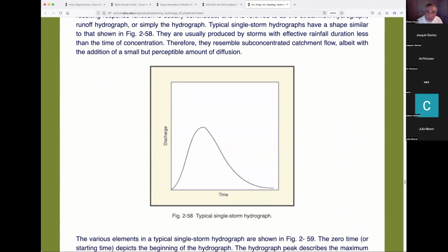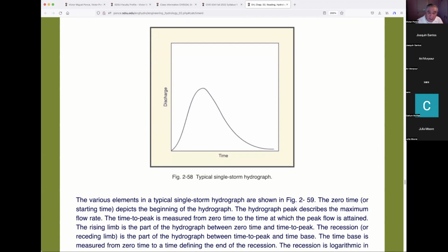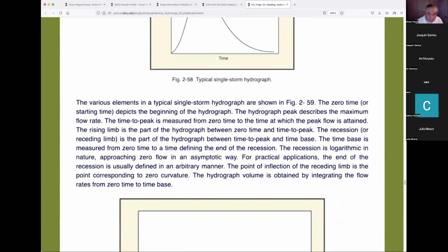It goes without saying that if you had a hydrograph that had peaks, it means that the flow was all kinematic and subject to no diffusion. And that has happened, by the way. It does happen. In the steeper watersheds, typically with slopes more than 1 or 2%, you will find peaks. But those are the uncommon. They're not the normal situations.